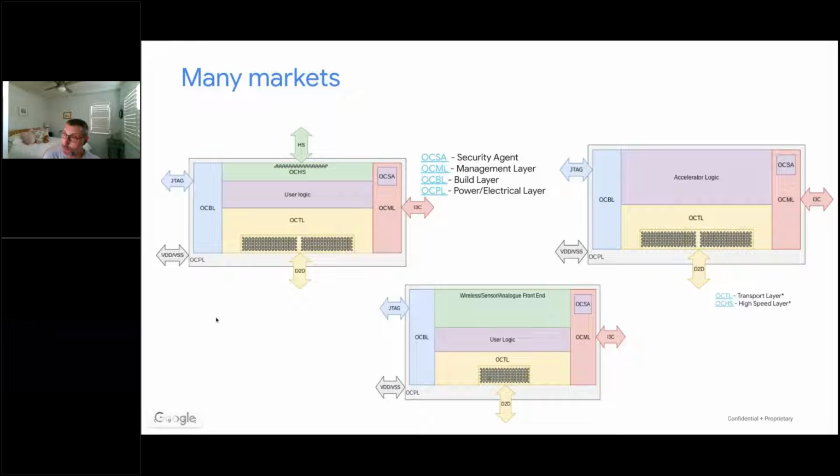Again, we're trying to make it as broad as we can, addressing as many chiplet use cases as we can envisage. We probably didn't cover them all. On the left there is an IO style chiplet die with a high-speed interface layer. We deliberately don't say what chiplet that could be. We looked at it as a layered specification, much like IEEE 802.3 and those kinds of specifications.